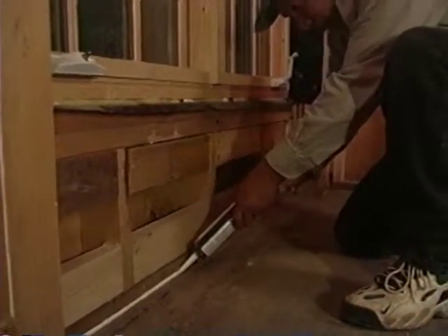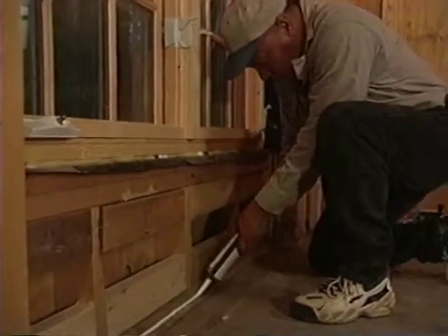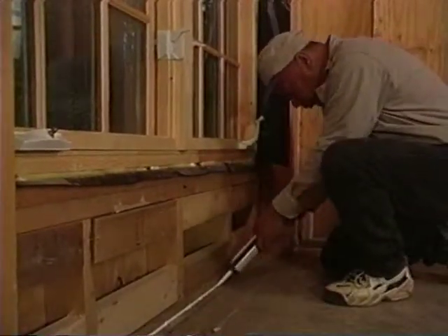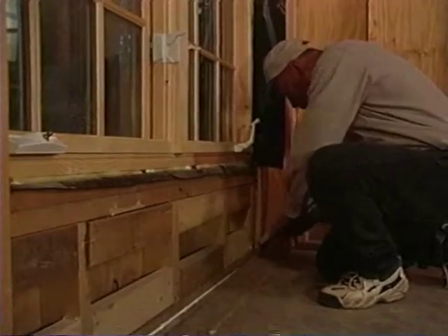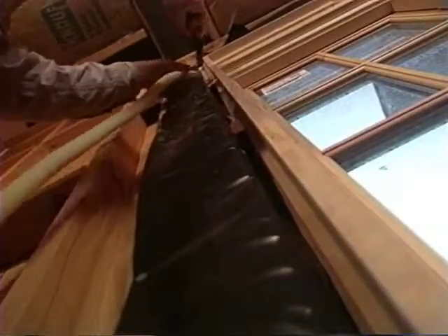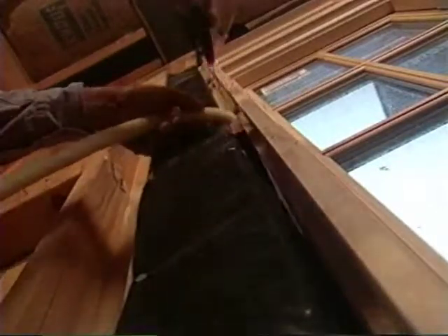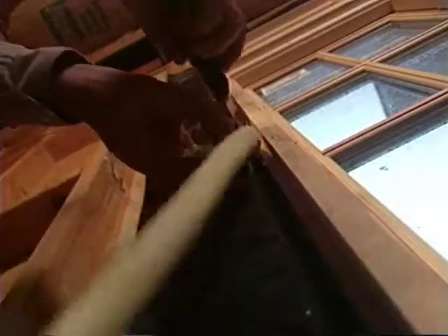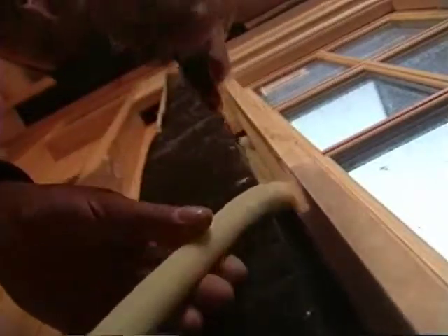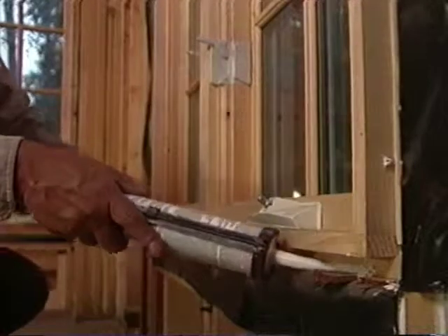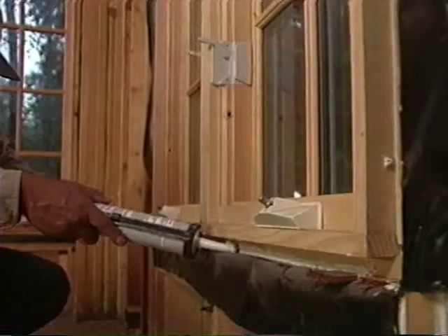Air sealing is an important part of eliminating air leaks. Luis Ramos is a trained air sealer and insulator with nearly a decade of experience. When sealing around windows and doors, Luis uses a closed-cell foam roping in between the window and the framing. Stuffing fiberglass in this gap will not work because fiberglass is not an air barrier. He also caulks wherever he has cut the roping to make sure the gap is completely sealed. It's also important to seal any holes left by plumbing and electrical penetrations.